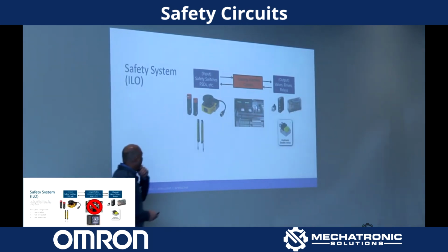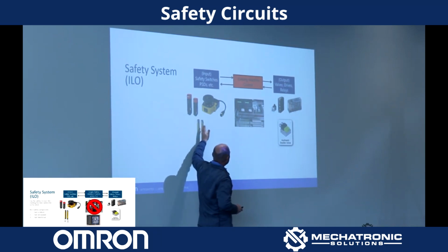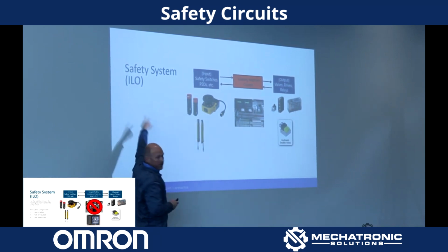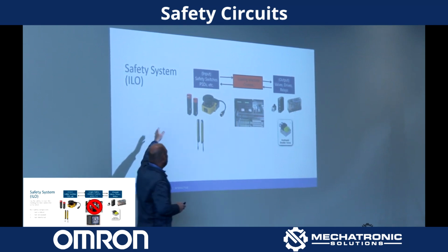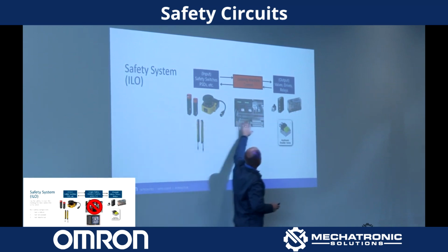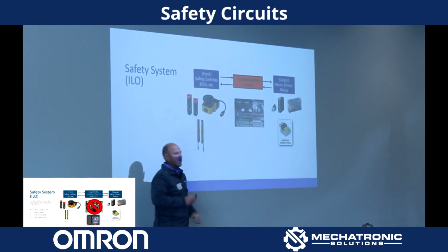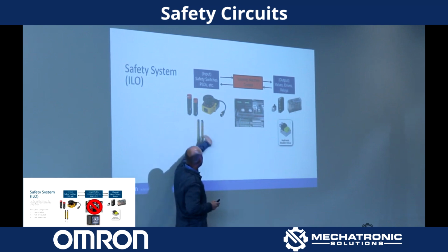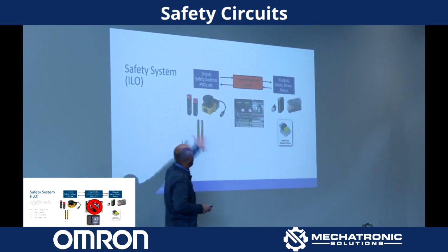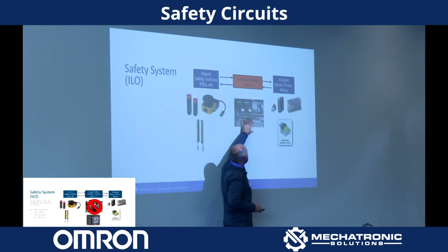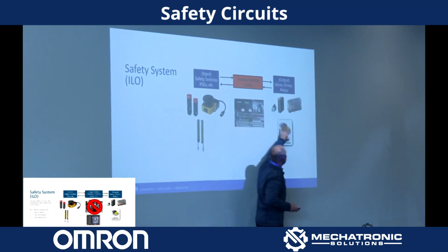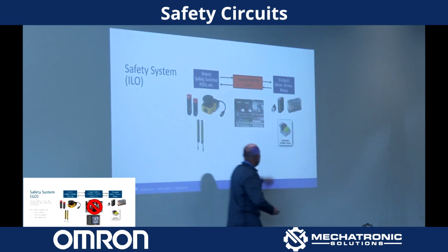So the idea is that we don't want to tie our input devices directly to outputs. We call it I-L-O, you heard that before? Input, logic, and output, right? Input would be our safety device. We've got a door lock on the machine, or an area scanner, or a light curtain, and we breach the light curtain, whatever it may be. That sends an input to the logic or to the control, and then that's going to send an output to some device, or another relay, a drive, a valve, whatever that may be on the other end.